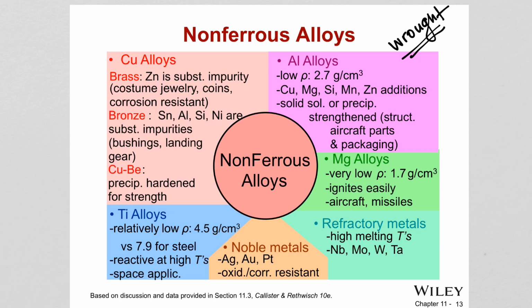You can also think about aluminum foil, right? They are able to produce very thin aluminum foil from aluminum by rolling. We're gonna take a look at the manufacturing techniques. It is due to the FCC structure of aluminum, which provides ductility, but they have a low melting point. That's the problem. Therefore, it restricts their usage.